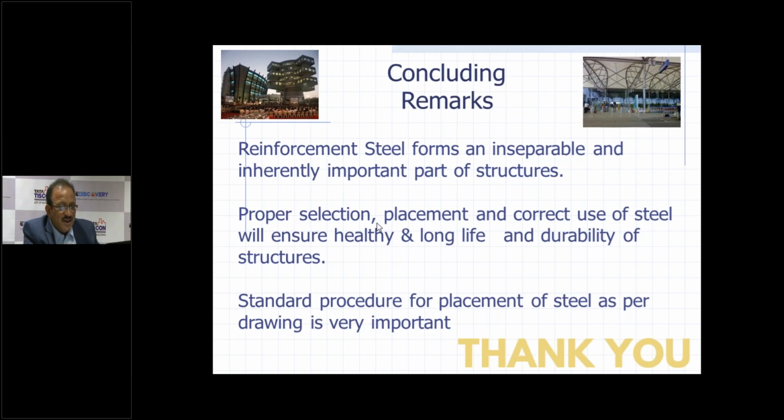So we never try to put more steel reinforcement for increasing the efficiency of the structure. In fact, under reinforced structures are preferred, because you get beforehand alarming warnings by cracks which appear in the structure because of the loading or whatever. So it is always preferred that we should have an under reinforced section.